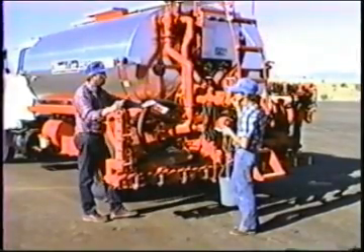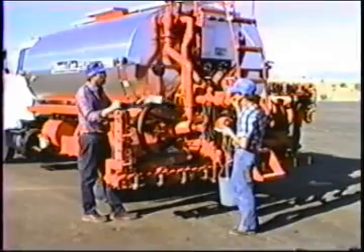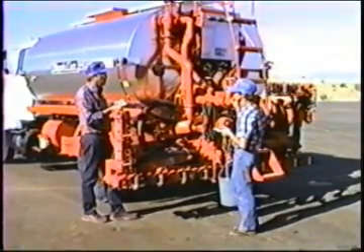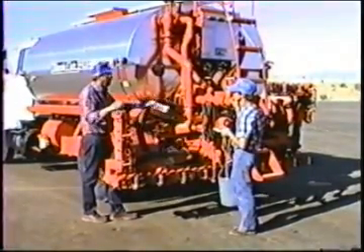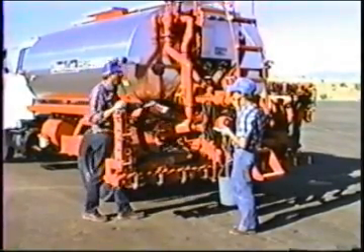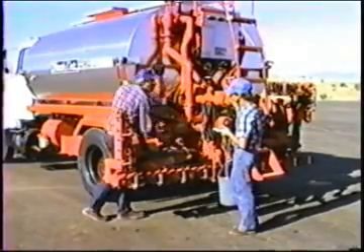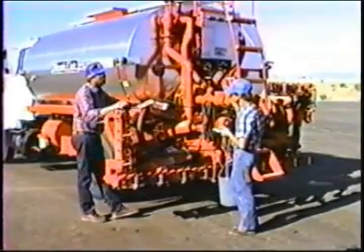It takes those three pieces of information and calculates the required gallons per minute, just exactly as we did with the cardboard slide rule. Then it adjusts the asphalt pump to that required gallons per minute based on feedback that it sees down here on the gear tooth sensor.